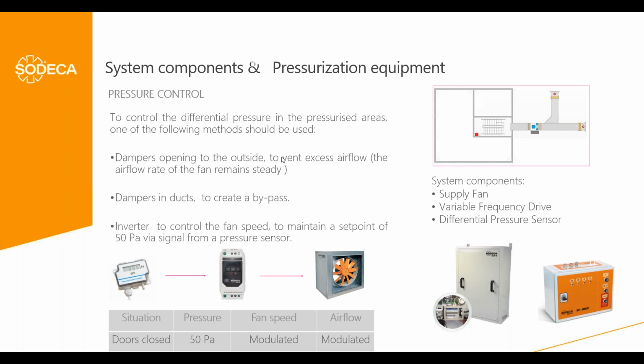So it sends a signal to increase the capacity of the fan. That increases the flow, so the overpressure increases a little, so the pressure sensor says, now I have 12, and this continues until the system increases the velocity till it arrives at the maximum 50 Hertz and the maximum airflow capacity. Remember that in that case, the goal is not to maintain this level of pressure, the goal is to maintain this air velocity corresponding to this maximum airflow.